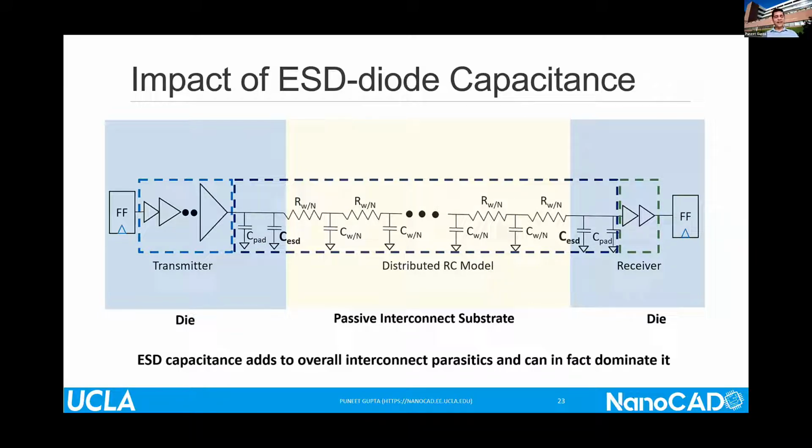So conventional GPU, CPU tile systems, unfortunately, don't work well in that scenario. And there are lots of applications which fall into that bucket as well. Wherever you are immensely limited by aggregate memory and bisection network bandwidth, that's where this wafer scale type integration, at least in our opinion, would work really, really well.